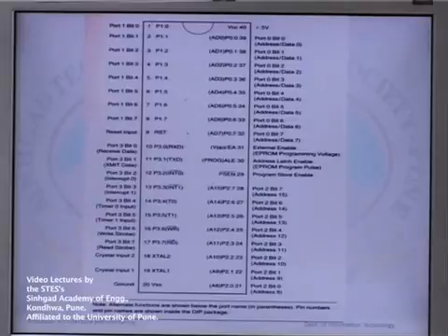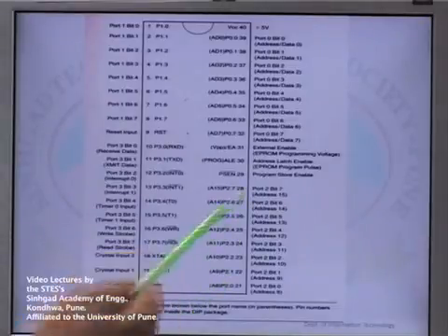Pin number 21 to 28, all these pins are nothing but the port 2 pins. That is, they can be used as simple input output pins for port 2. If there is no intention to use external memory, then these port pins are configured as general inputs or outputs.